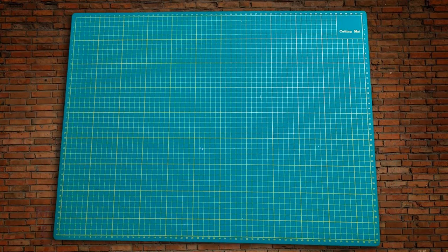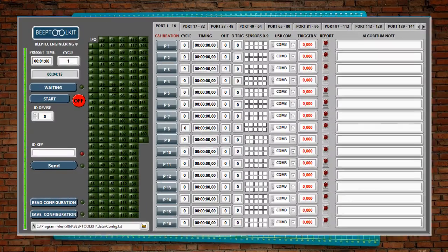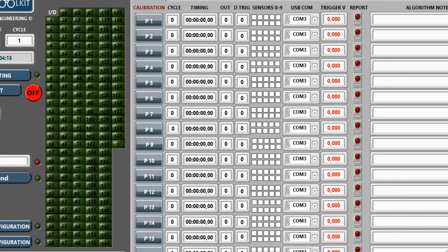After the start, we give a pre-start pause of 5 seconds. For this we use port 1 to set the time. Next, we start the servo motor. For control we use the second port and the first channel. In this case, we turn on the LED. Its control will pass through the second channel of the third port. We start the stepper motor. Fourth port and third channel.